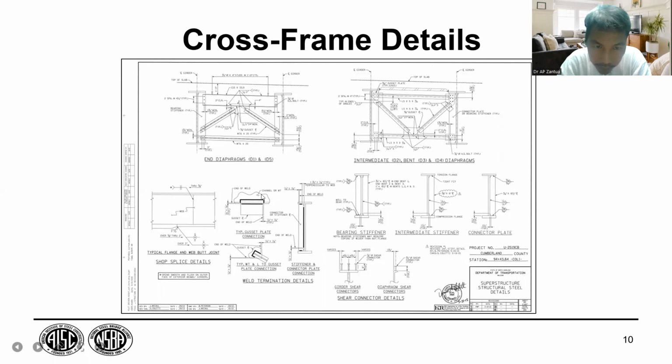Gusset plate. So again, important here. So again, cloud. Whenever there is a cloud, those are important information because it is with the cloud symbol. Actually, they are modifications, amendments. They are updates. They are updated size or shape or specification. That's why it is written in cloud symbol.